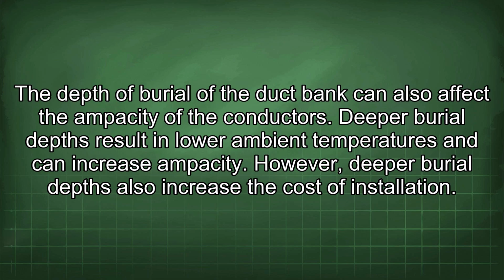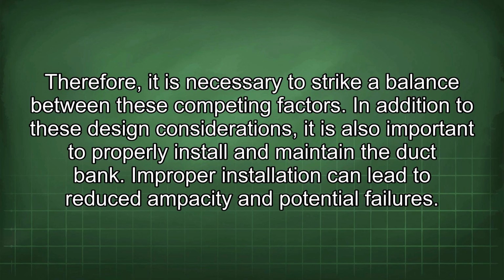The depth of burial of the duct bank can also affect the ampacity of the conductors. Deeper burial depths result in lower ambient temperatures and can increase ampacity. However, deeper burial depths also increase the cost of installation. Therefore, it is necessary to strike a balance between these competing factors.